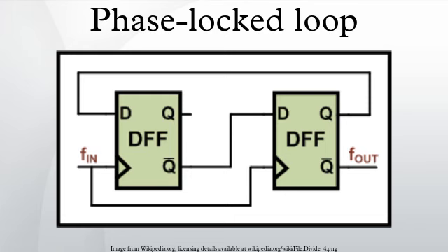The intent was to develop an alternative receiver circuit that required fewer tuned circuits than the superheterodyne receiver. Since the local oscillator would rapidly drift in frequency, an automatic correction signal was applied to the oscillator, maintaining it in the same phase and frequency as the desired signal. The technique was described in 1932, in a paper by Henri de Bellescize, in the French journal L'Onde Électrique.